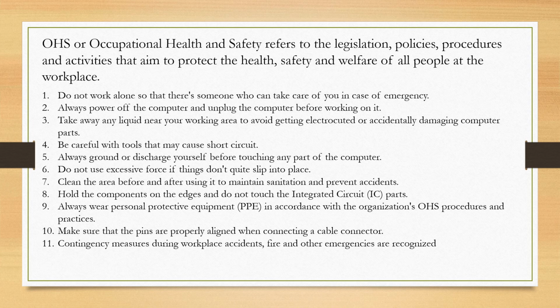Number 3, take away any liquid near your working area to avoid getting electrocuted or accidentally damaging computer parts. Number 4, be careful with tools that may cause short circuit. Number 5, always ground or discharge yourself before touching any part of the computer.